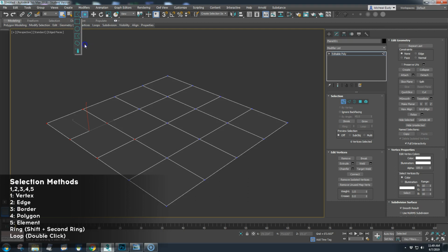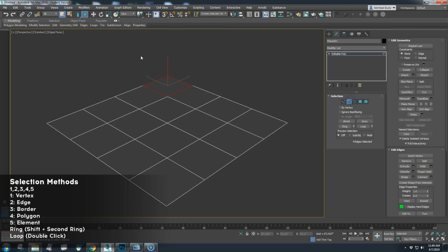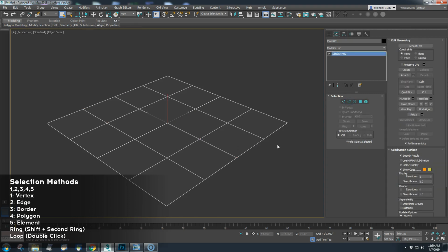Okay, and then there's a really fun one in here, which is a spray can. What this one allows you to do is click, hold down, and drag across, and you're picking things by dragging across them. So if I'm going to edges here and I click that, you can't have this one on inside. This one's got to be on crossing. And now anytime I cross across something, it's kind of like I'm painting a selection. So that's nice to be able to do sometimes for more organic selection. That comes into effect a lot of times if I'm wanting to create a more organic look.